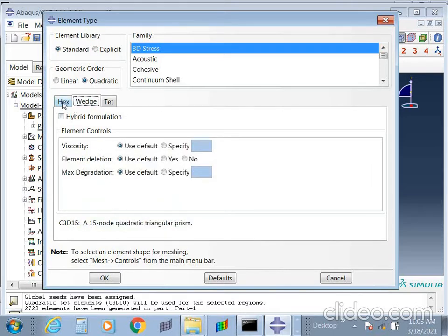And next, if I take a different mesh like hexa, it will give C3D20R, where R means reduced integration. These are the element types we typically use. They all come under 1D, 2D, 3D. For Abaqus they have different naming, reduced integrated or integrated.